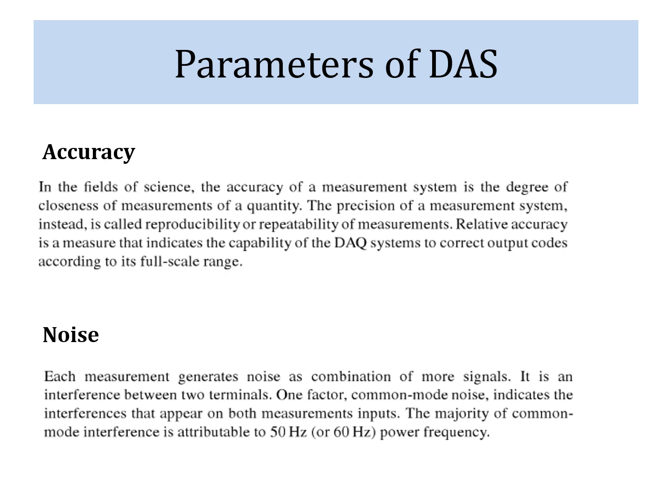Accuracy is very similar to what we have studied in measurement system, that is, it is the degree of closeness to the measurement value, means whatever the known value is with us, the closeness of that measurement value with the true value is known as accuracy. And precision means reproducibility or repeatability of the measurements. It means if the measurement system is giving you the same readings for the same input, it means it has the reproducibility to reproduce the same output for the given set of inputs.